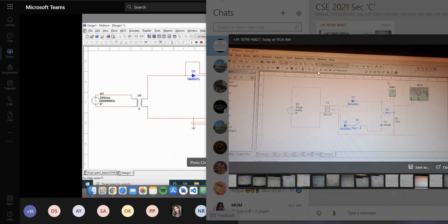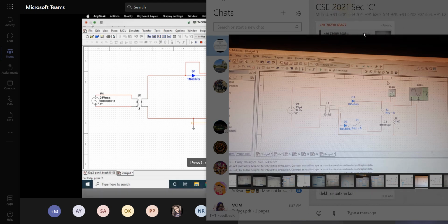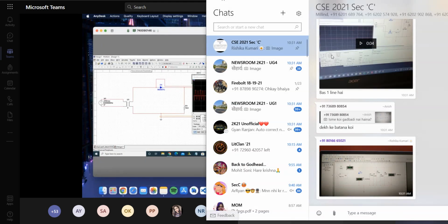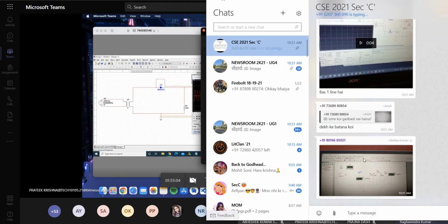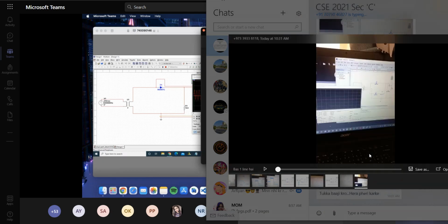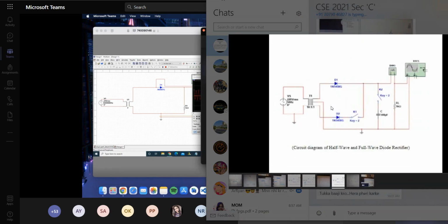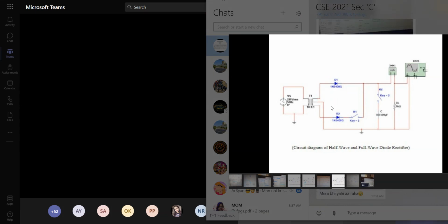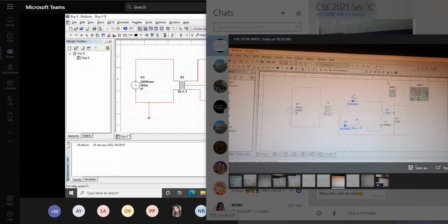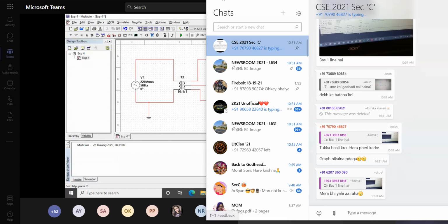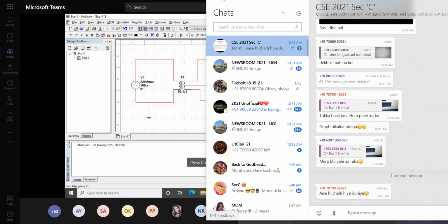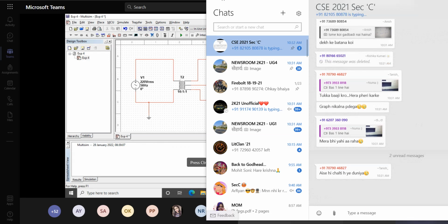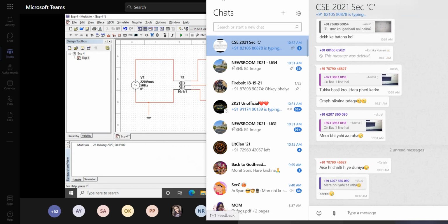Yes, you do. Anyway, this is what I was interested in showing you: if any electronic device is there, it has got some limitation. And why is this limitation coming? It's because of that PN junction, which is forward biased or reverse biased due to the applied voltage. When we make the PN junction forward biased, the depletion region decreases, and when we apply reverse bias, the depletion region increases.